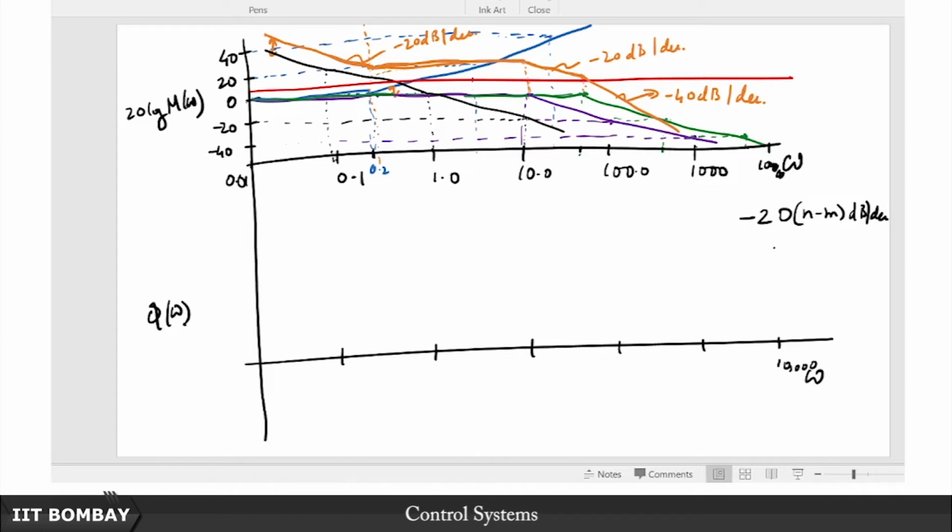So that's why in control theory we often say that all control systems are of low pass in nature. What it essentially means is, so that's another term you might encounter, low pass. These will only begin to make sense once you understand Bode plot. You see there are more poles than zeros in a typical control system, right? So n is greater than m.